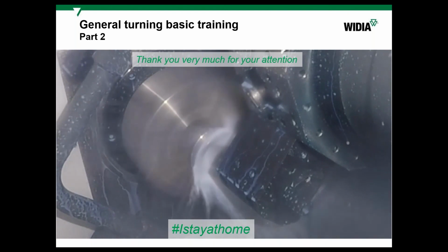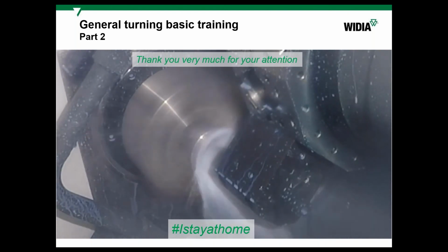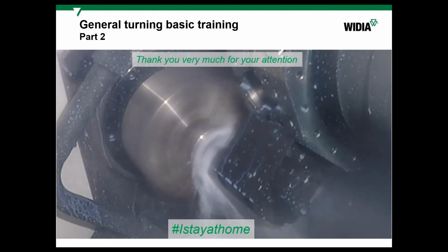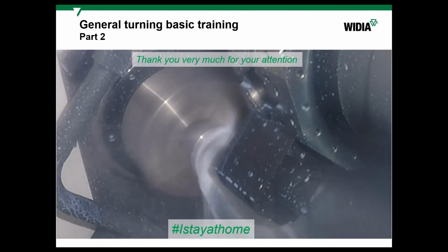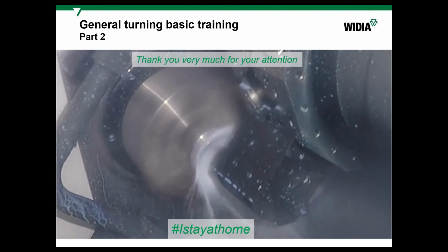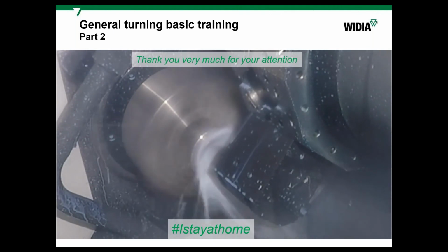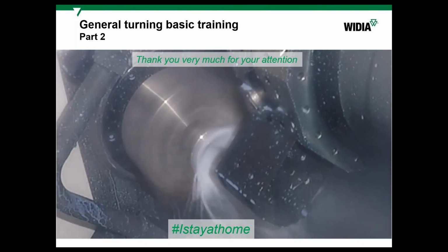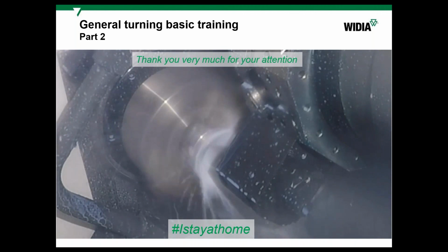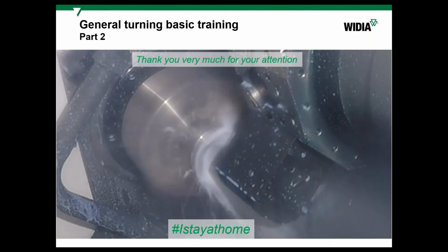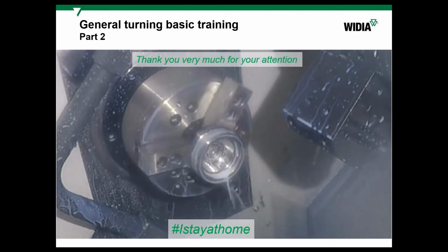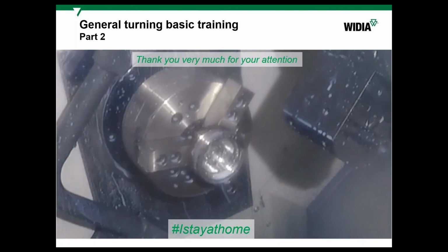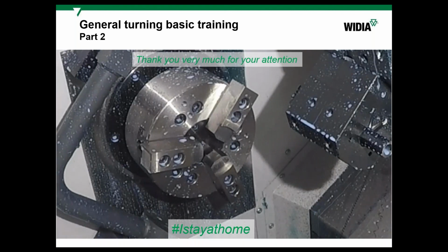What to do? To choose, for example, instead of a steel bar material, carbide. We also have it. If your overhang is bigger than 4 diameters, from 4 to 6 diameters, the first choice is a carbide holder. If you need to go even deeper, we have an assortment of anti-vibration bars from 50 diameter of hole, for 10 diameters and for 15 diameters.